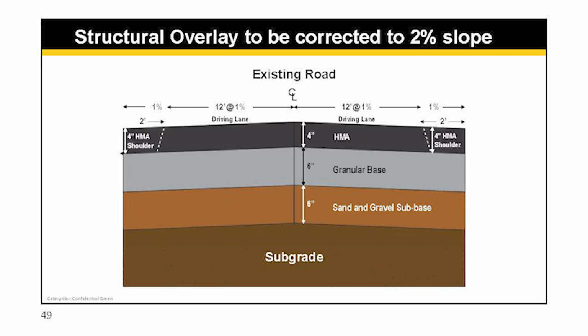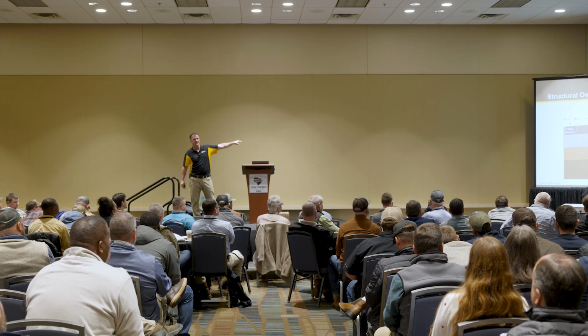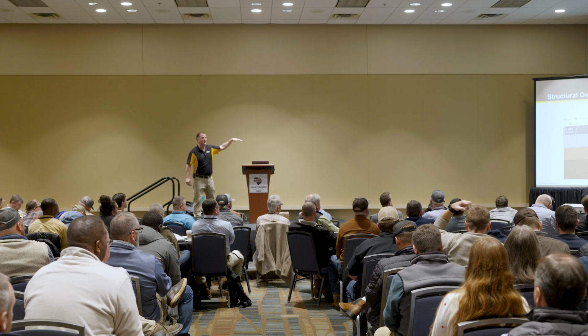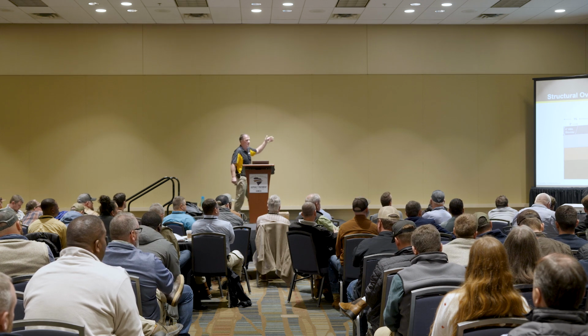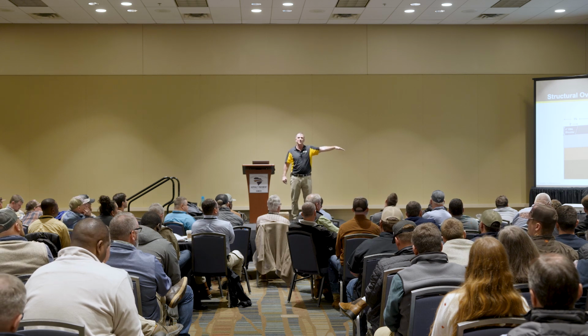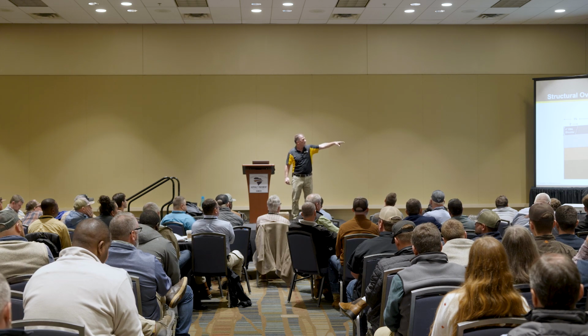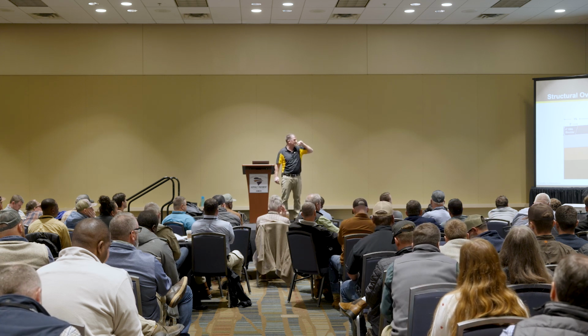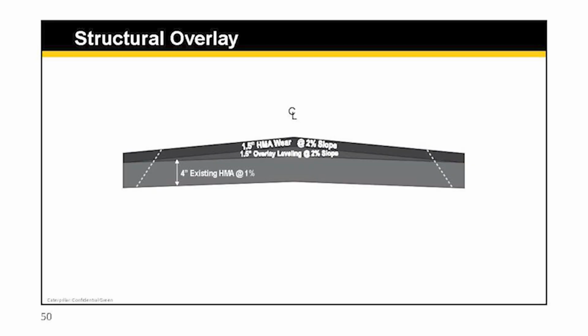Another example, here's if we look at the existing asphalt, 12-foot wide lane, but what's the catch here? You look at that percent cross slope is 1%, right? What are most specs now? Probably always was. This probably was 2%. So 2%, right? So we got to fix this. So we're coming in to pave it. They want it 2% wide, or slope, I should say, after we pave it.